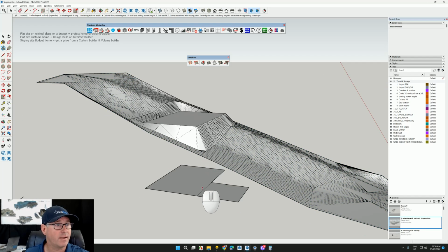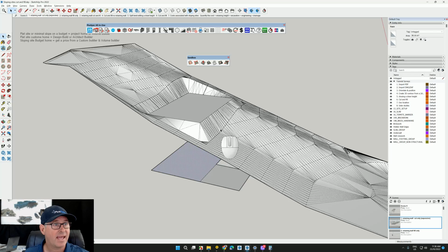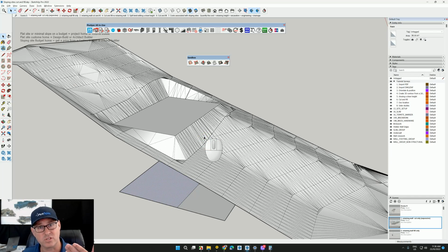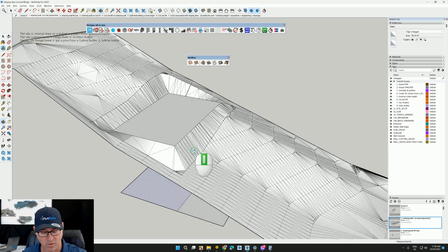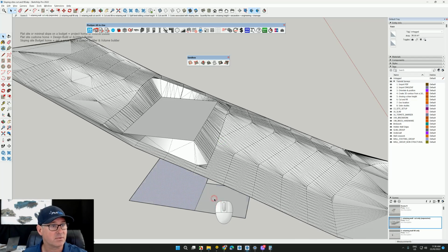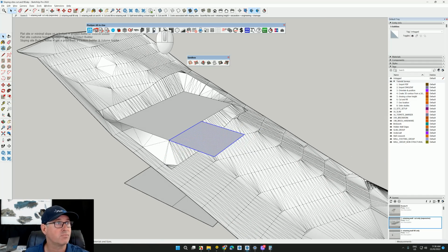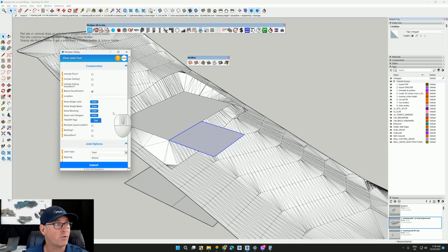right, now we can go to here. I can probably do better, and then out in this section out here I would actually probably have bearers and joists or steel, lintels and so on, and essentially what I would do is grab this face, move, Control, bring that up to there. I would then use my flooring tools, and whether it be suspended slab or floor joist or whatever it might be, we're going to put in a floor here.